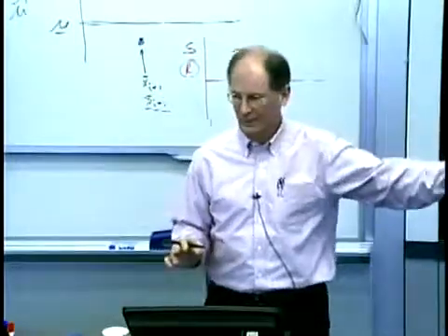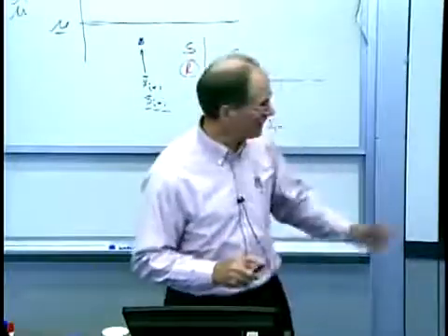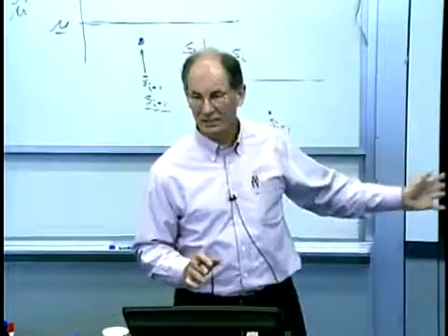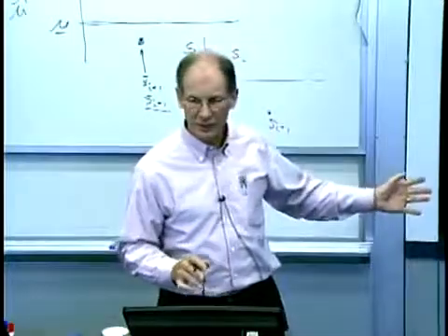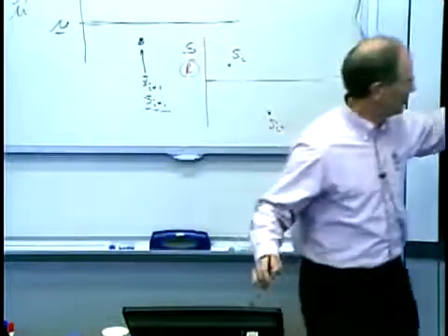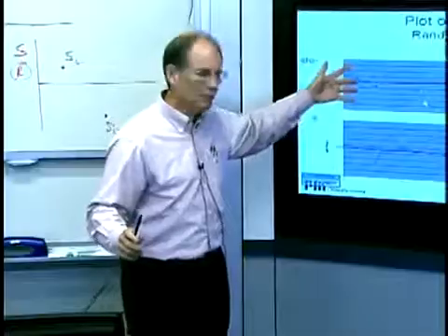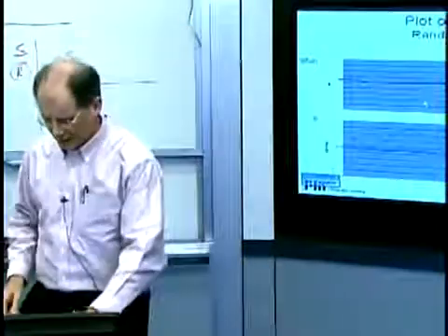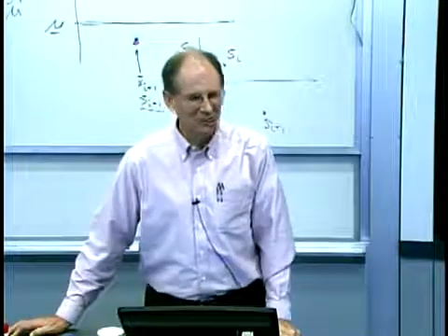This has already happened. So the first thing I need to do, and this is part of the art of SPC, is I have to look at that and say, does it look like it's in a state of statistical control? And frankly, at this point, you eyeball it and you say, well, I don't see anything that makes this look non-random. And we're going to quantify that in just a second. But what else could I do looking at a run of data like this to say, yeah, it kind of looks like it's in a state of statistical control?